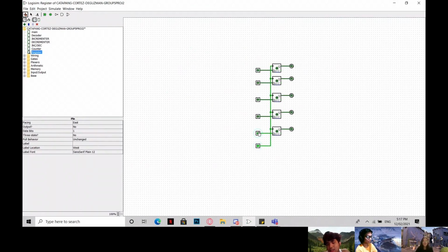So this is for the D flip-flop of our project. The D flip-flop is also known as the delay flip-flop. The D flip-flop captures the value of the D input, which is on the left side of the circuit, at a defined portion of the clock cycle, such as the rising edge of the clock, and that captured value becomes the Q output. So the purpose of the D flip-flop is to capture the data and to transmit the data to the output. At other times, the output Q does not change. That's why it's called the delay flip-flop.